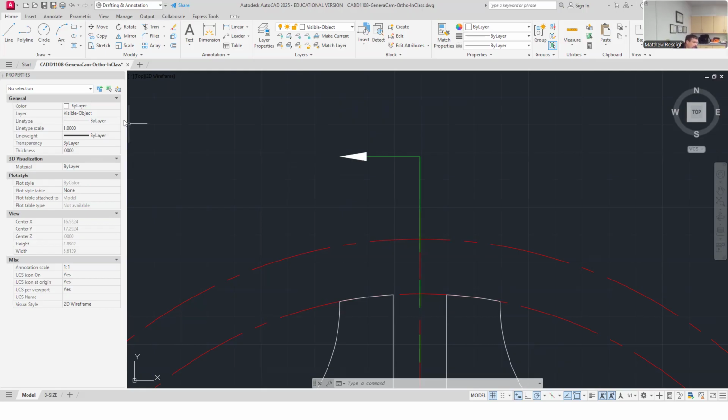So I'm just going to do a block. Remember, your block is your friend. We don't do a ton of blocks. We've done one, the title block. We haven't done any write blocks yet, but that's kind of how the title blocks on these new templates that we're using were created, because I'm using the ISU templates. Those title blocks were created with a write block. So they allow you to input data and parameters and kind of make the block a smart block. I wish they'd call it smart block or something, but it's a write block, a W block.